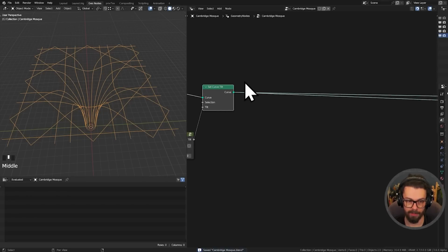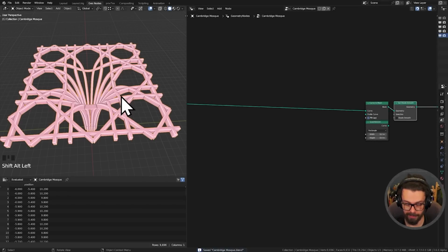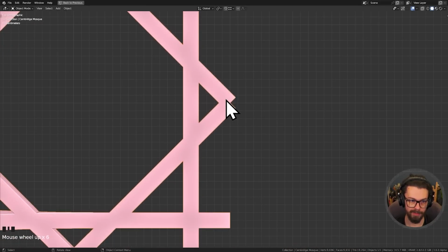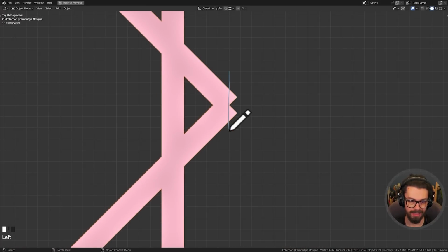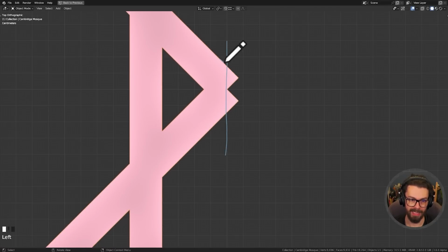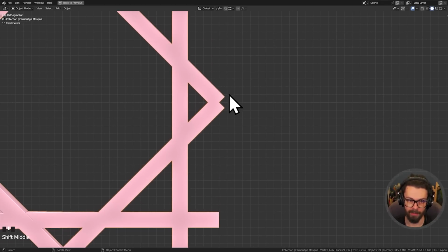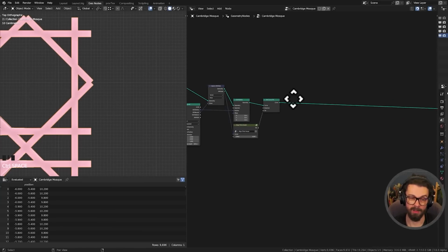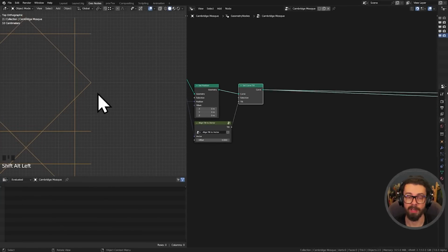Also another thing that's important, actually, just before I carry on, if I go into 7 up here, after I've skinned it, this point, right, this line that comes down, after it's been skinned, you are offset by half of whatever your profile width was. Obviously we don't want that to happen. We don't want the next one to be starting over here and having a little dead space. We want to make sure that we are properly coming off the correct location. So to do that, you just basically base it on the size of the curve. That's going to work fine.